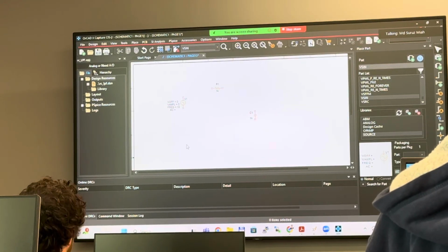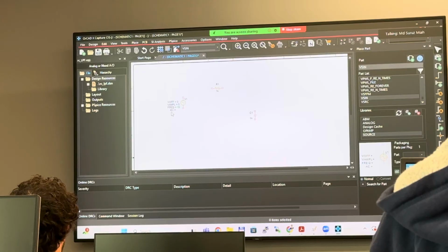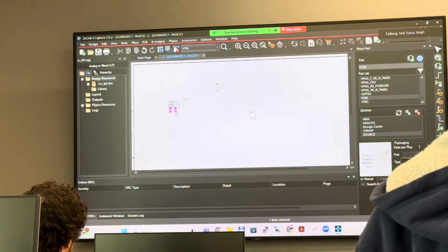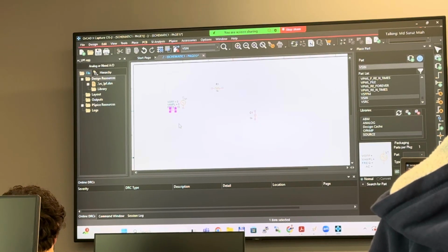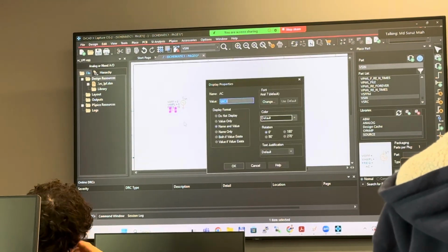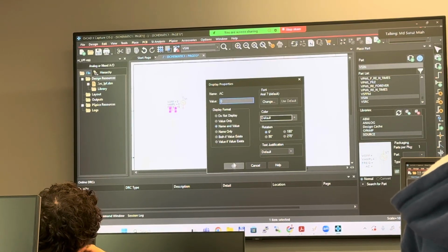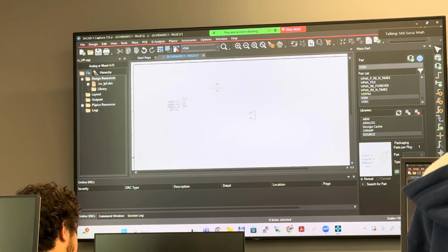You guys are okay? You guys follow me? Okay. Now AC, because we will be simulating, we want to see the output in the time domain. So the AC part, not in the frequency domain, the AC part, I'm just going to place it 0 for the moment. Now we have defined our first source.